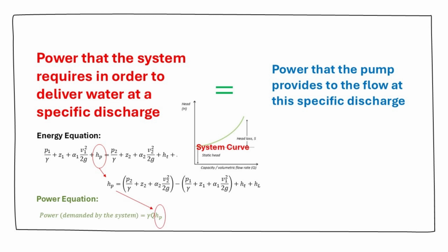A system curve shows the total system head required over a range of flow rates. In other words, the system curve is a graph that shows pump head required by the fluid system at different flow rates. It is determined by calculating the resistance to flow of all the components in the system, such as friction losses due to pipe diameter, length, and roughness, elevation changes, and fittings and valves. For a given system, the system curve is fixed and does not change unless there is a change in the system's configuration or operating conditions.